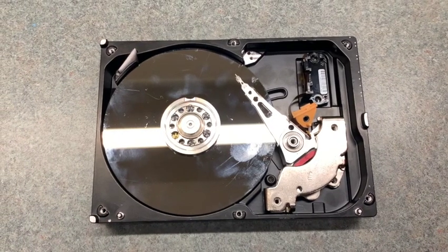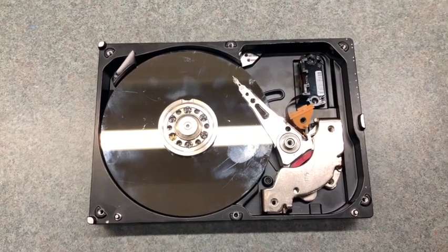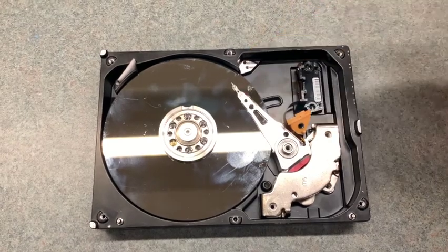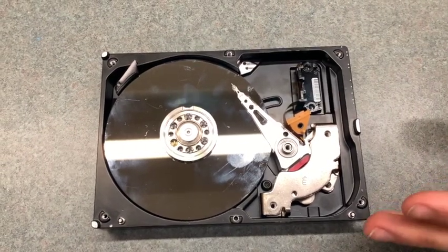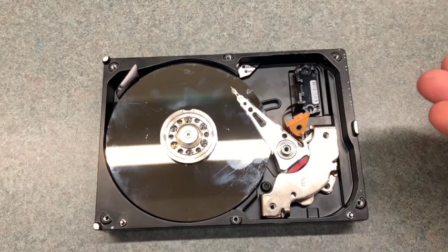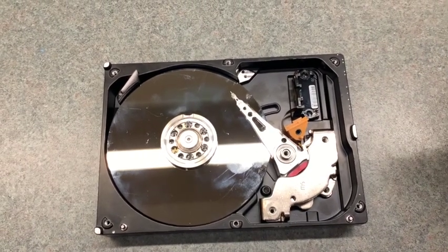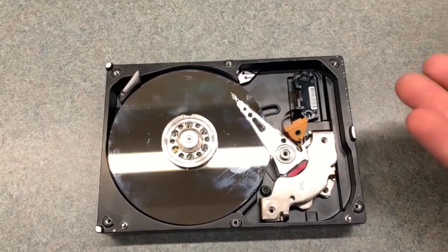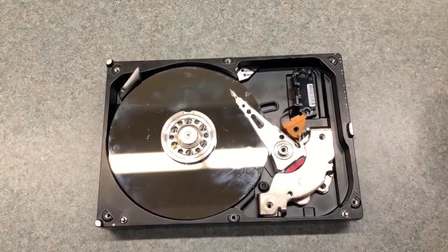This is a hard disk drive. We're going to look at the two fluid mechanical components here, the air filter and the head. The head is a very interesting fluid mechanical system because it needs to be kept off the disk to prevent crashing. It's done by slightly angling the head, which creates a pressure which lifts it off the disk. We're going to look at that in our video.